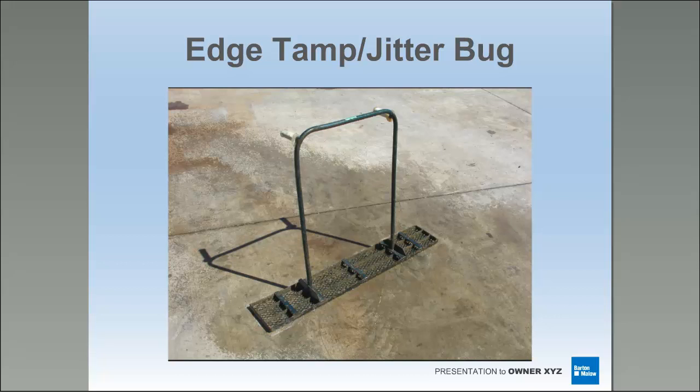Now here's the downside to it. If I'm going after an aggregate exposed polish, you don't even want to see this on the job, because all it's going to do is prolong your cut. You're going to cut a lot deeper to get through that cream to get to the aggregate. So if you're doing an aggregate exposure, you don't want to use this. If you're doing cream or salt and pepper, this tool is going to help get you there, especially on the edge. Definite benefit there.